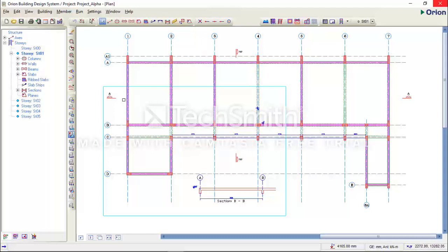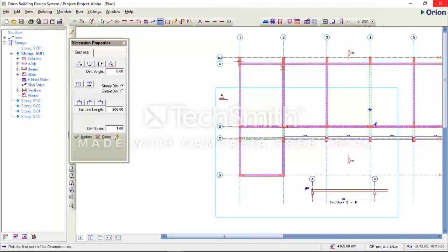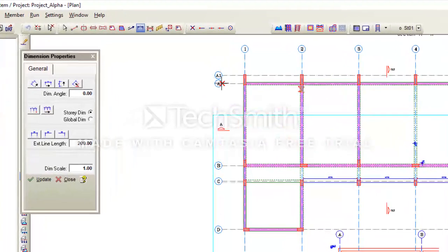drawings, the first thing you need to do when you want to carry out structural analysis of your slab element in the software is to draw your strip lines along the structure. So before I do that, I would like to dimension my structure, my grid. To do that, I can click on the dimension button on this member toolbar here. I'll click on it, and I want to dimension between the lines A to B.